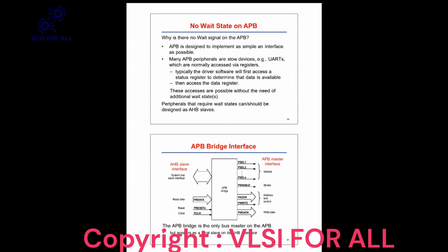I'll explain with and without wait state. From the master side you will drive write data, control signals, clock, everything. But from the slave side there are three signals you will be collecting: read data, slave error response, and the ready signal. So focus on that ready signal. That ready signal will decide the wait state or without wait state concept. If you are not going to wait for the slave whether it is ready or not, and by default you are assuming that the slave will always be ready, then you will put this concept in the category of no wait state.